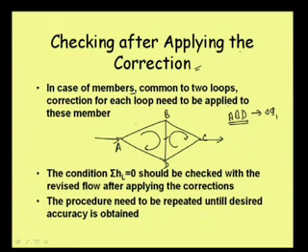Let me write q1, q2 and q3, assuming the discharges are q1, q2 and q3. After all our calculation, the k values are k1, k2, k3. So we can calculate head loss in each pipe: k q1 square, k q2 square, k q3 square. Then we assume flow in this direction, this direction, and this direction is this one.